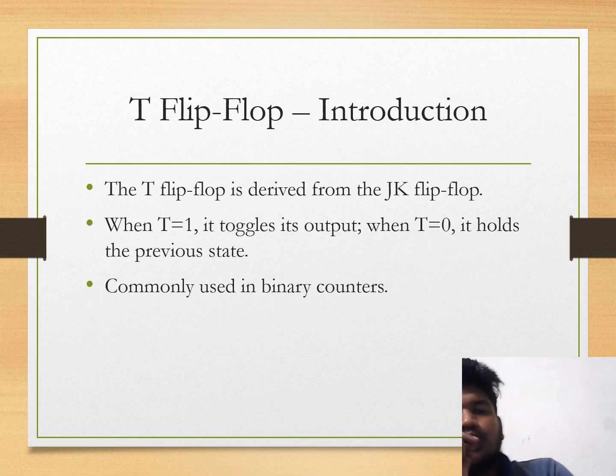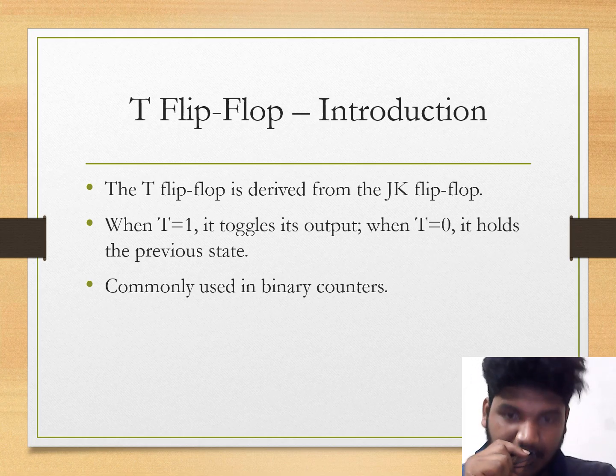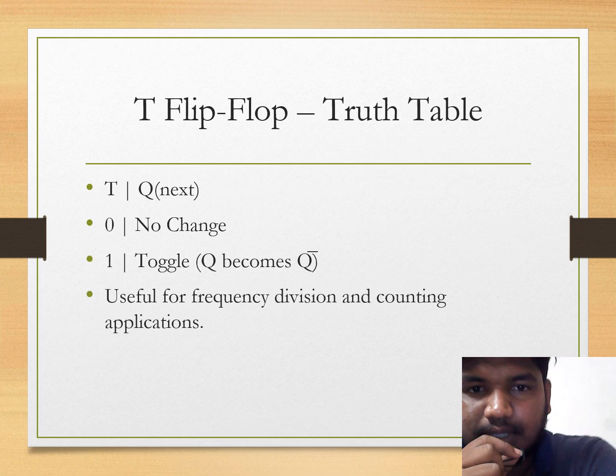Now I am going to talk about the T flip-flop. The T flip-flop is derived from the JK flip-flop. When T is 1, it toggles the output. When T equals 0, it holds the previous state. It is commonly used in counters.